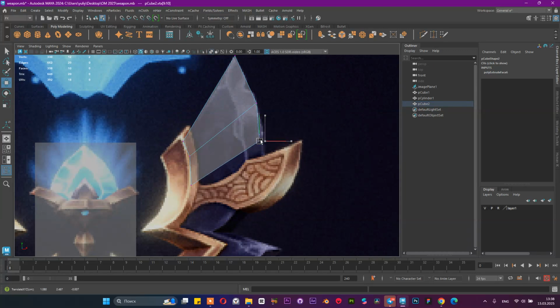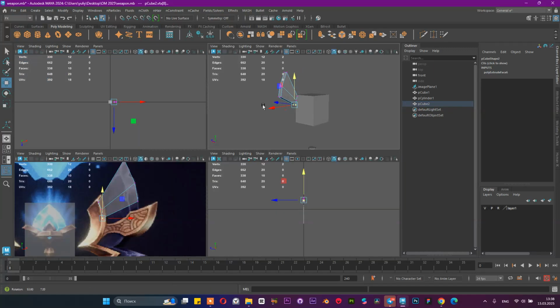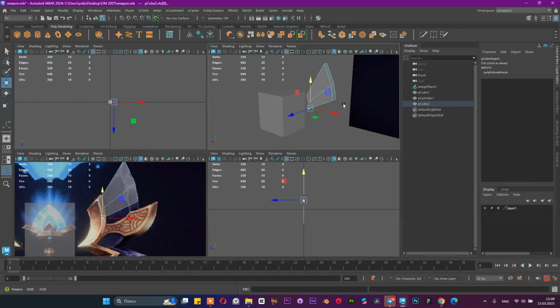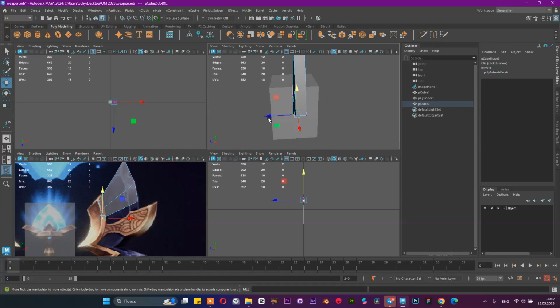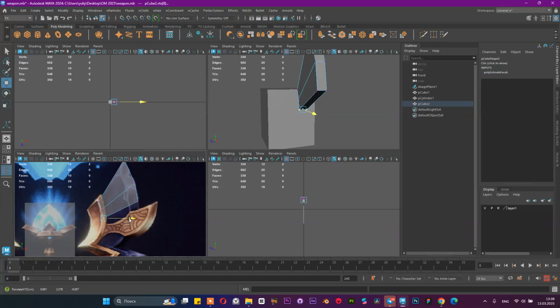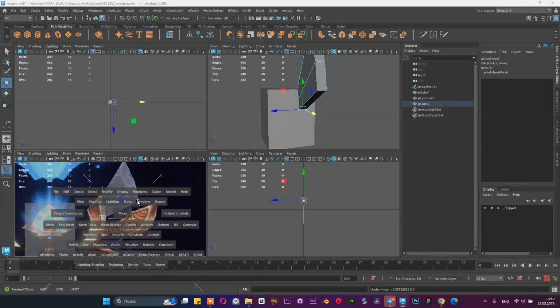I'm moving my vertices only in this area, not in the perspective mode, because I need to keep these vertices according to the x-axis without any changes. We shouldn't put these vertices beside this perspective. That's why I'm using this manipulation only in the front view.